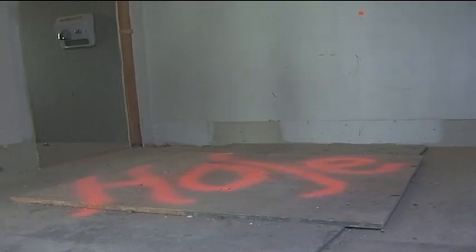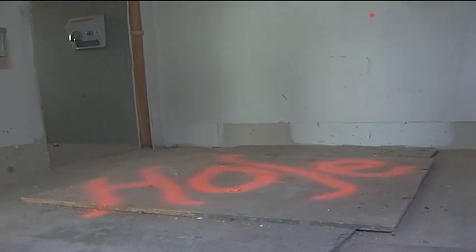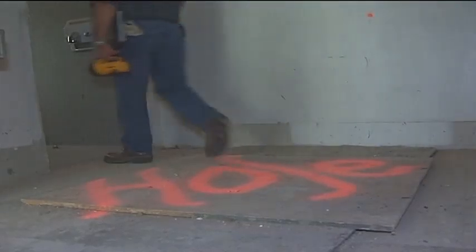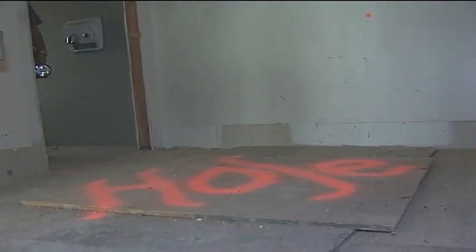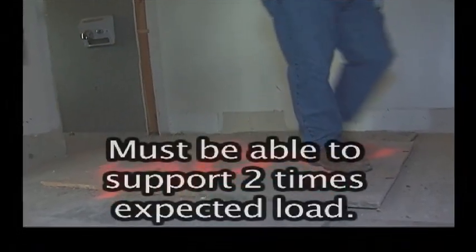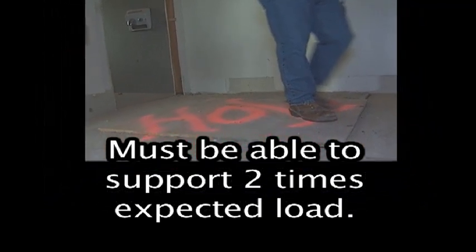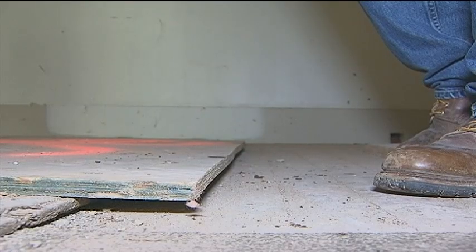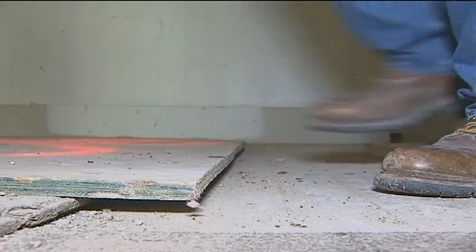Covers should be used to keep employees from falling through holes in walking and working surfaces, and be able to support at least twice the axle weight of the largest vehicle that might drive over the cover, and at least 2 times the weight of employees, equipment, and materials that may be imposed on the cover at any one time. A cover should be well secured to prevent accidental movement and be marked with the word hole or cover.